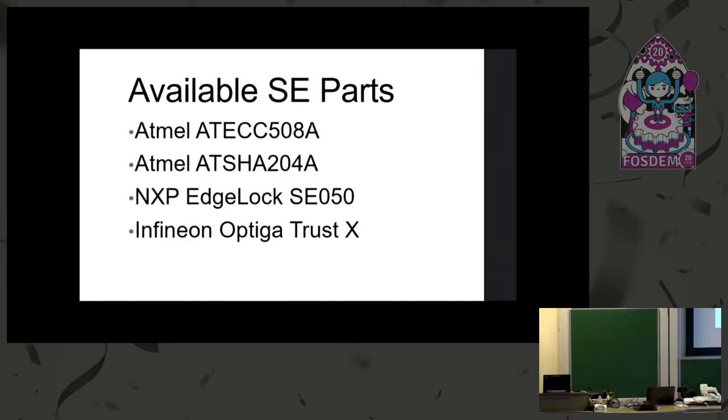So can't draw, but the SOIC chips, they're the ones that you usually see with the legs on the side. You can solder those very easily, and those are the Atmel ones. The NXP is a bit more difficult. The Infineon OPTIGA parts, I believe, are like the NXP. They're QFN and under. So these are kind of the things that you might find in very small devices.